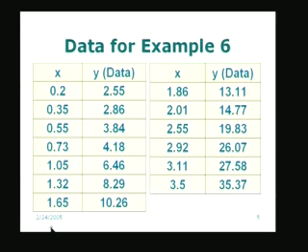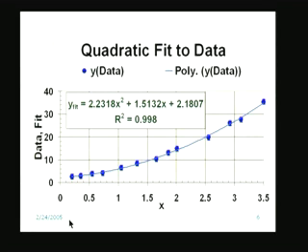So, let us look at the plot before we go on to the goodness of the fit. So, what I have done is I have used the Excel program to choose the proper trend line, and in this case the trend line was a polynomial. So, when we choose the polynomial as a trend line, it will show like this: polynomial, POLY stands for polynomial. So, this is automatically showing that we have chosen a polynomial, and I have given the title here quadratic fit to data. That means I have chosen a polynomial with degree equal to 2.